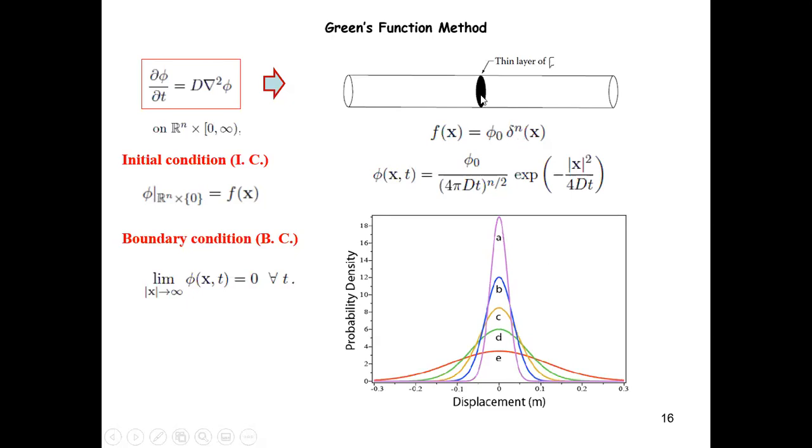If you allow the system to evolve further, the carbon is going to penetrate more to both sides of this bar. Mathematically, this means that the distribution becomes a little bit wider. That comes to the blue curve. You see that now the height right here gets lower. This means that more carbon escapes from this high concentration region and penetrates into the surrounding regions, and the penetration gets thicker because the region of penetration gets wider. This simply goes on.